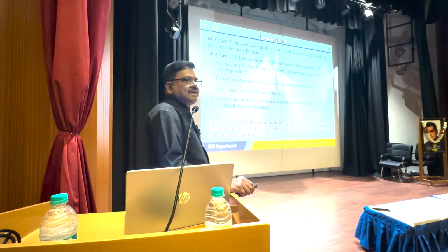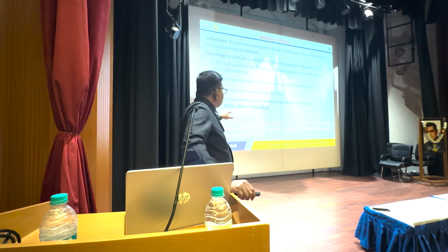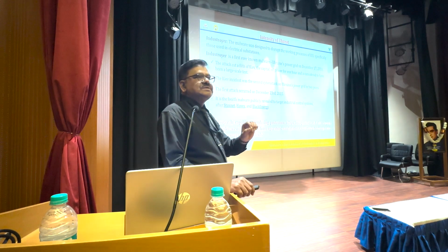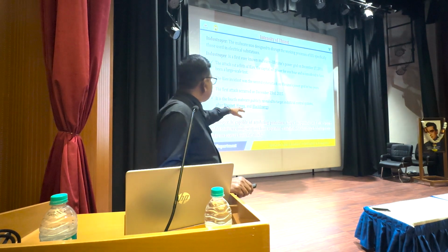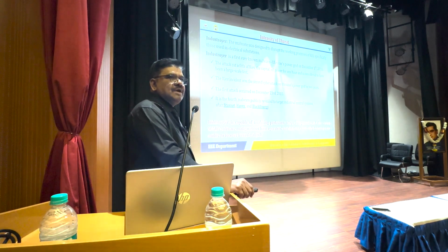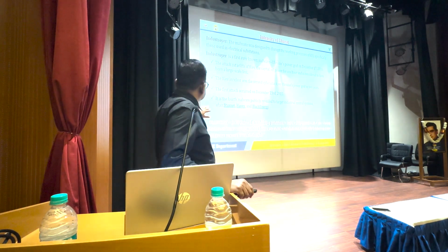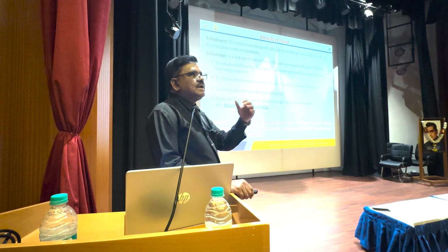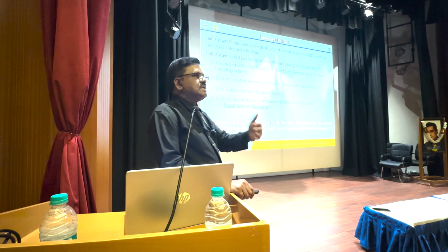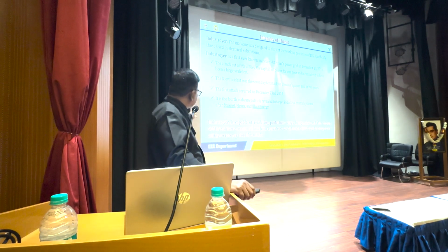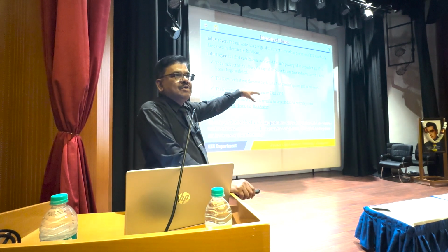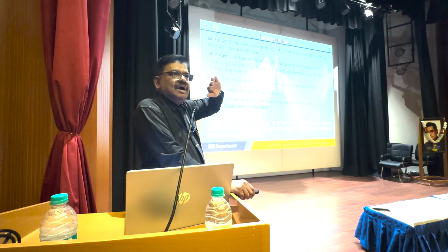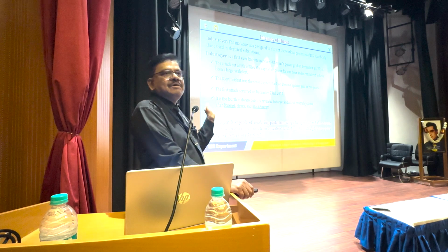So what will Industroyer actually do? It will make the protective relaying systems in the power system irresponsive. That means protective relays become irresponsive. Then it will wipe off all the SCADA software available in the operator's workstation. Obviously it leads to a plant shutdown or a partial shutdown. So it will have a direct effect on your protective relaying system. It will not operate, so your circuit breakers will not be opened or closed unless the operator gives access.